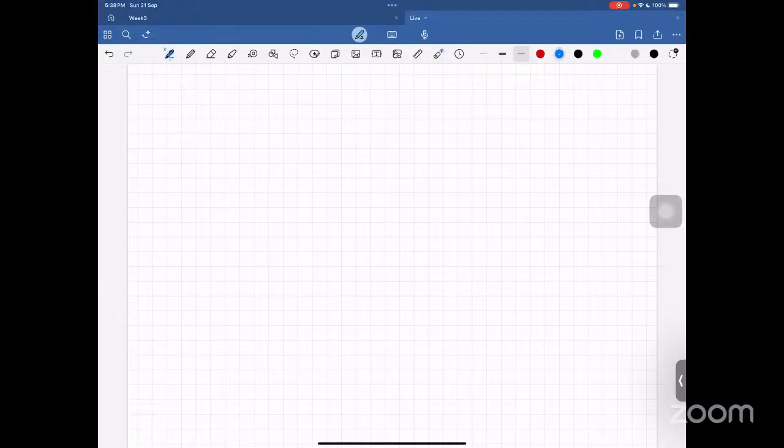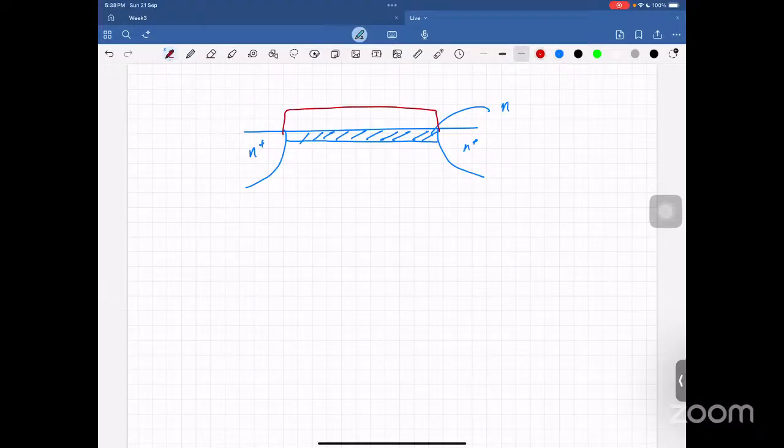Let's look at it carefully. What we are saying is you're talking of a MOSFET. So let's take an N-channel MOSFET. So N plus regions, source and drain, and there's a channel, right? This is the linear region where you have an N-type channel. And then on the top, of course, we have the standard oxide and then the gate. This is the gate and this is oxide, and then the substrate will be, let's say, p-type. This is what you have, correct?